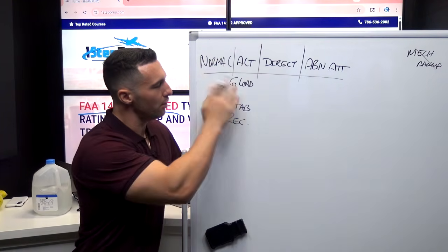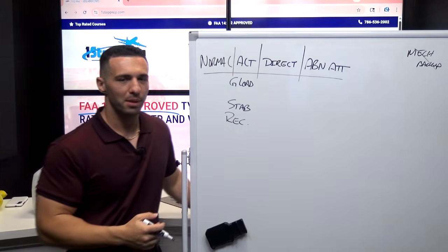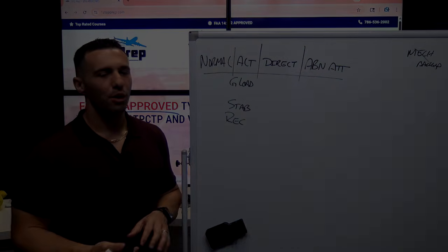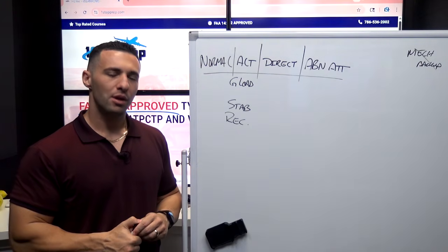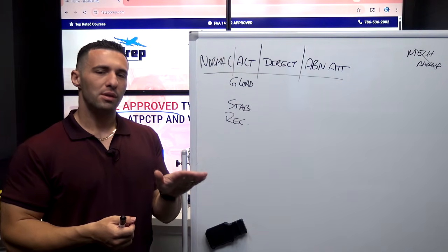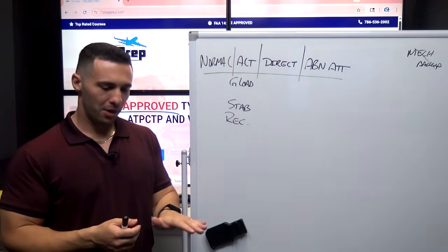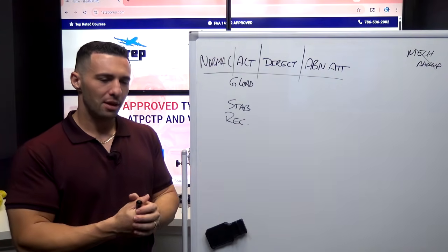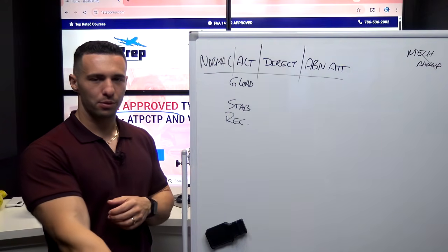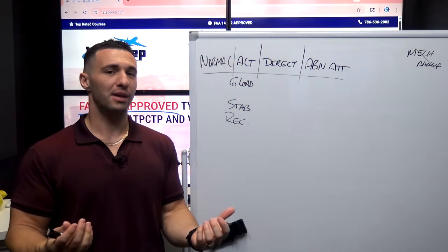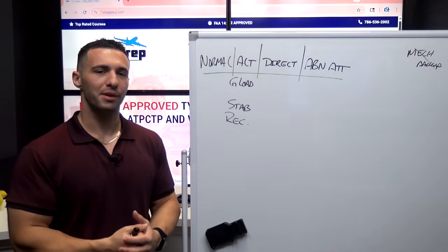So the G-load we're clear on because we talked about it, but let's go to the stabilities. I have something referred to as high-speed stability, and then I have low-speed stability. High-speed stability is comparable to your high-speed protection, where it brings the nose up. The high-speed stability will very much give you that nose-up pitching moment, right? So we can start to reduce the airspeed. But the thing is, I can grab the sidestick and just bury it forward, and there's nothing that it's going to actually do to prevent me from doing that, and I could very much overspeed the airplane.